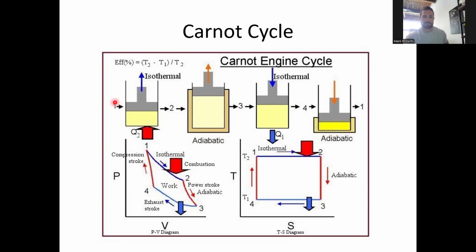And then we can take this and heat it back up, and go through this cycle again. So one of the ways that we can describe these cycles is that we can generate a net positive amount of work. The net positive work comes from the work associated with this expansion. So we have heating that causes the cylinder to move up, and it does work on the environment. So that creates a positive work.